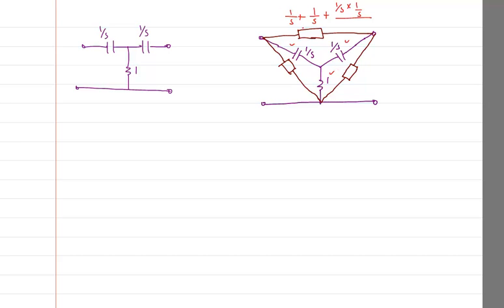So if you want to find for this case, you take the two branches on either side, and the third branch is this. So divided by the third branch, which here is 1, this would come out as 2 by S plus 1 by S square, which you can get as 2S plus 1 by S square. Am I correct? So that is going to be that one.